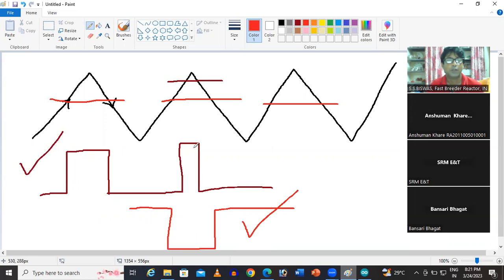And now you know, if these two pulses are going to a complementary switch, the transition should not occur at the same time. So we need some gap. You see, this is that gap.